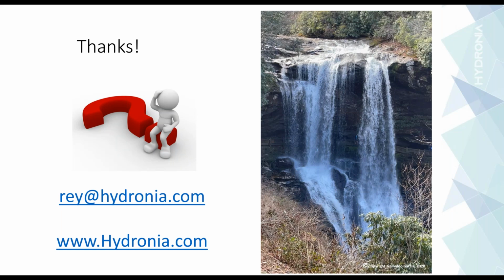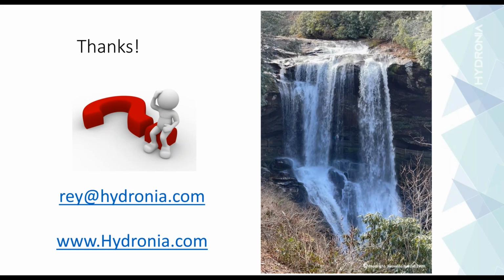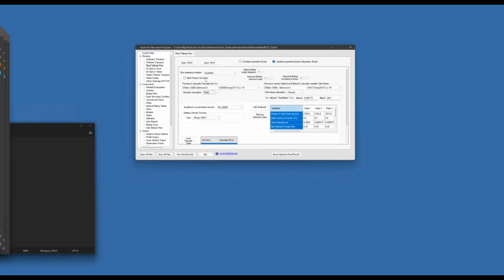And let me see if I can show it to you. In the 8.05 version, you will have this option here that says bed fraction evolution. With this option, you will be able to simulate how the bed granulometry changes in time and space as well.